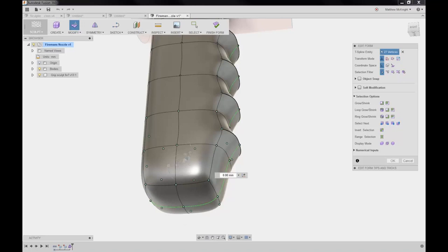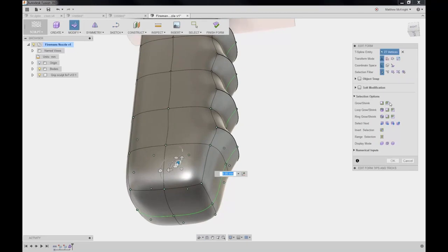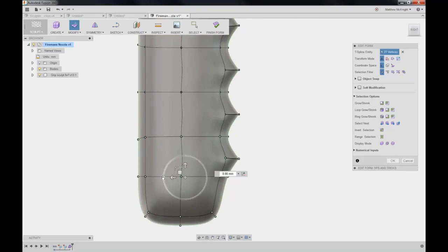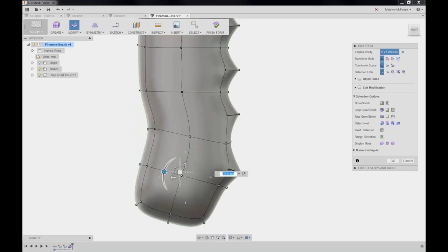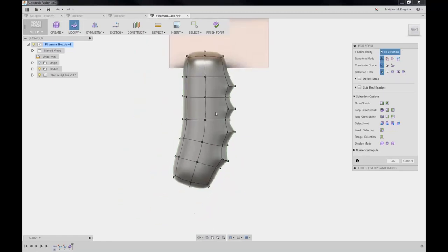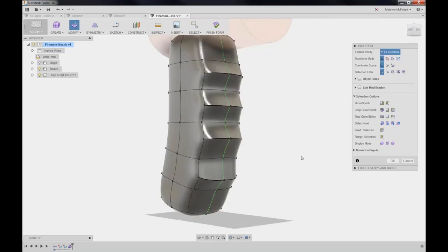And you can see it's gone through and it's grabbed a whole bunch of additional vertices, growing those up. We could shrink those down if we didn't want them, the additional ones in place. But we can now use these to manipulate our geometry. So we'll rotate them. Gives us a nice transition down at the bottom, and we'll position them over a little bit further. So we've got a little bit of a change, an arc to the end of our handle. Now the one thing that you'll note is that one of our vertices didn't move, and that's because when we used our grow command it actually didn't grab that vertice.